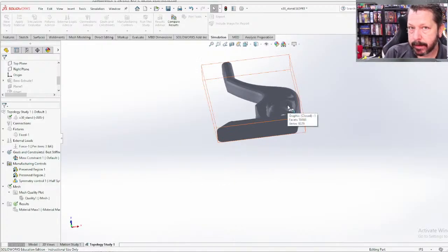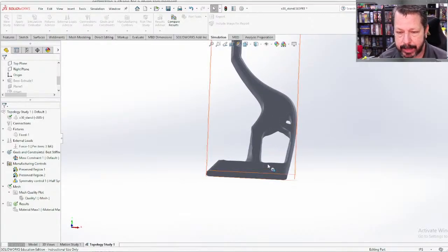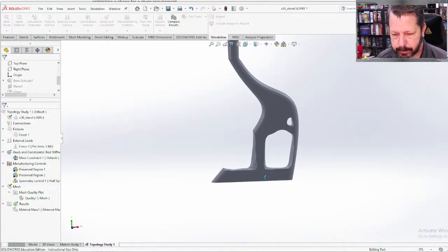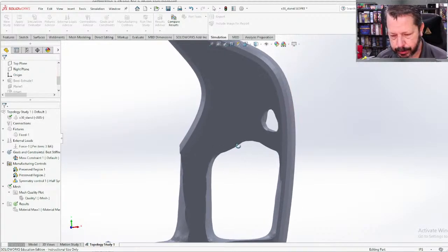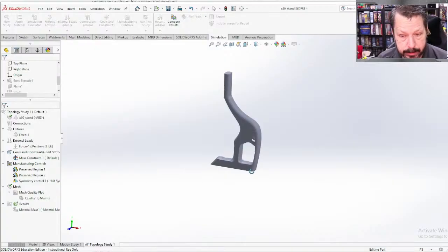It did not create this geometry specifically with the idea that it's going to be 3D printed, and I don't want supports or anything. So it didn't think about overhangs or any of that stuff. Although I think it would probably print okay with no supports. These right here might be a little bit shallow of an angle to print with no supports. Not sure. This one in particular. All right. So that's one thing you could do.